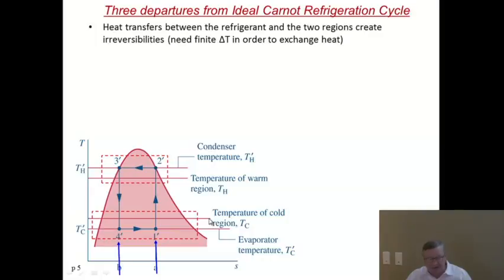If you want to keep your cold side at this temperature here, indicated by my cursor, you have to have the evaporator of your refrigeration cycle at a lower temperature here, so the heat can go from this temperature down to that temperature. That is an irreversible loss.